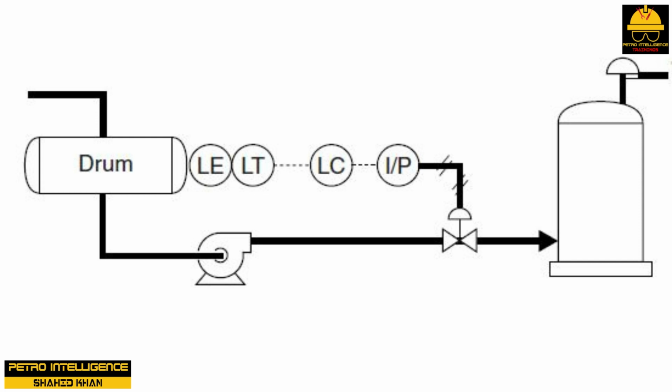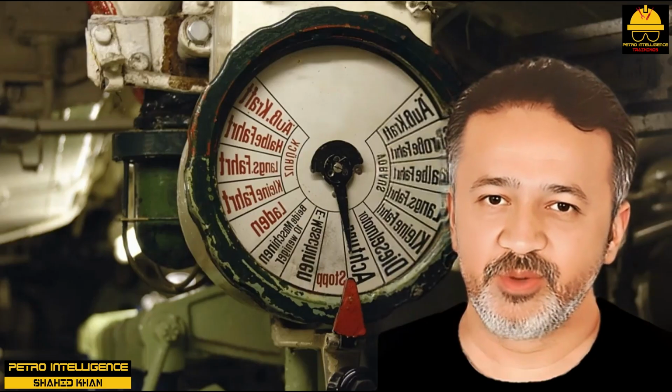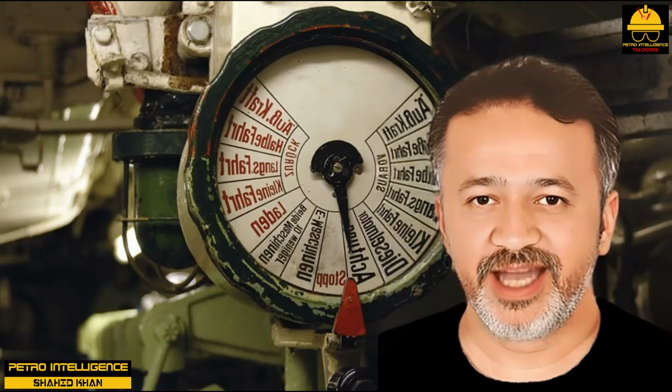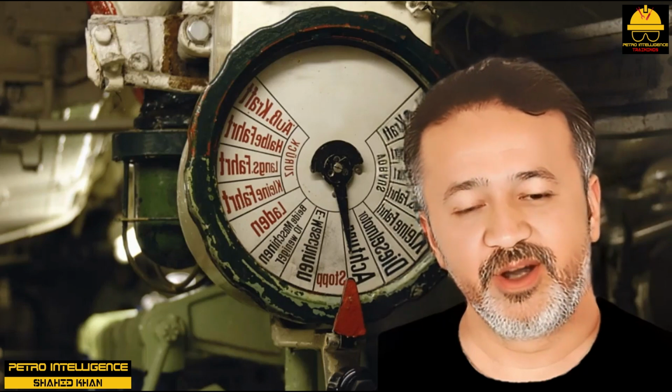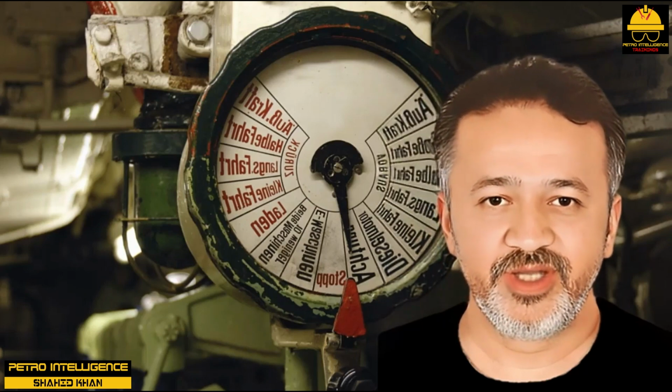Basic elements of a control loop. The key component of automatic control is the control loop, the group of instruments that work together to control a process. As we have seen, these instruments typically include a transmitter coupled with a sensing device or primary element, a controller, a transducer, and a control valve. Process plants contain many control loops that are used to maintain pressure, temperature, flow, level, and composition.